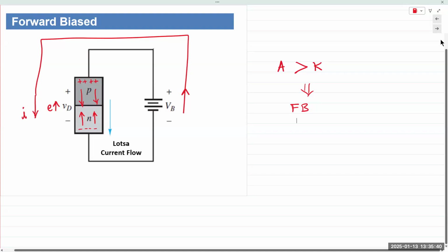It means that in the end result, both p and n-type materials have both electrons as well as holes available to carry the charges. But because of the large dosage that is introduced into the material, we have excess of holes in p-type and excess of electrons in the n-type material. But they both also have holes as well as electrons.